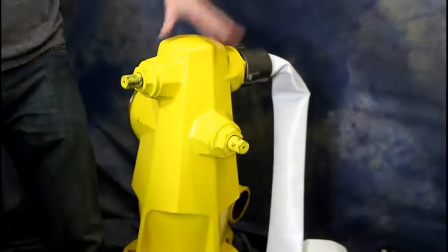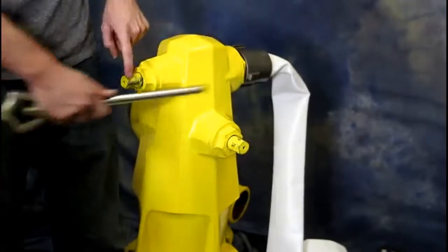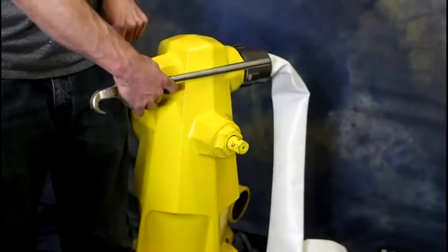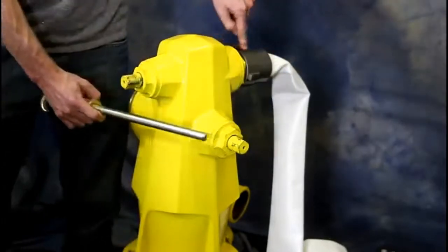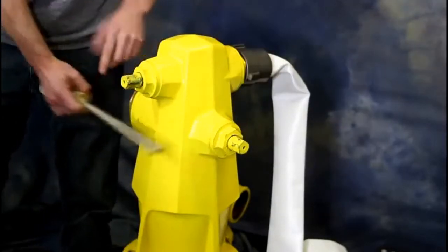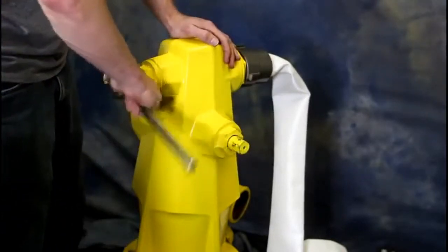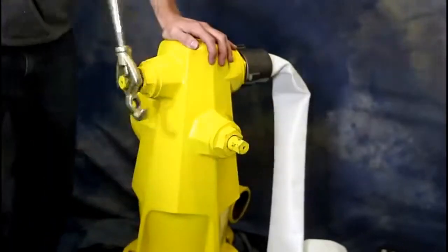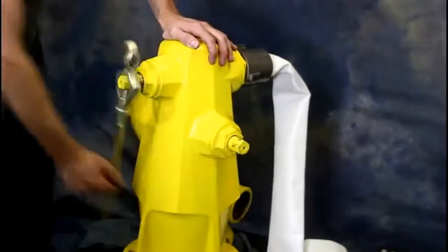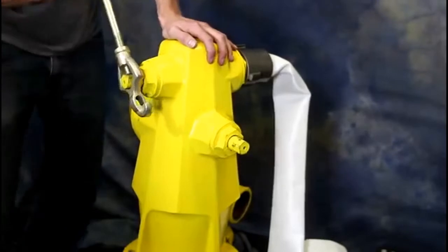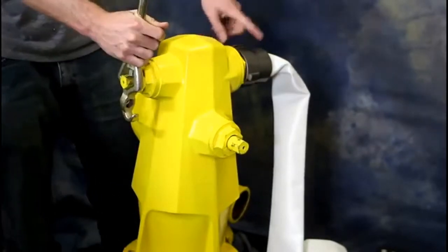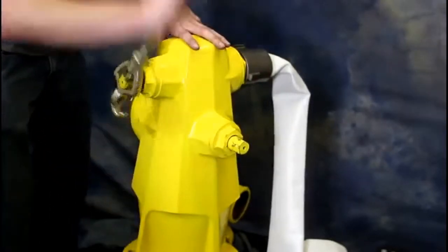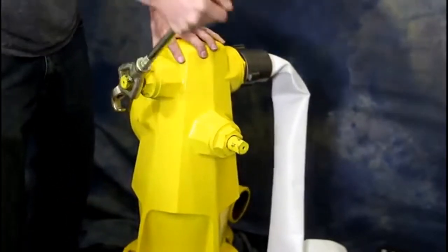To open it up and start the water flow, you're going to take the bolt that is completely adjacent to whatever side you're trying to open. So this top one is going to go to the 2.5, whereas this lower one is going to go to the 4. All you do to open them is stick your hydrant and spanner wrench on and open it right up. Now when you're trying to close these and you're finished, sometimes you'll see that these are leaking. If that's the case, take your hose off and open it up, blow some water out, close it back up, and hopefully it'll have removed that debris.